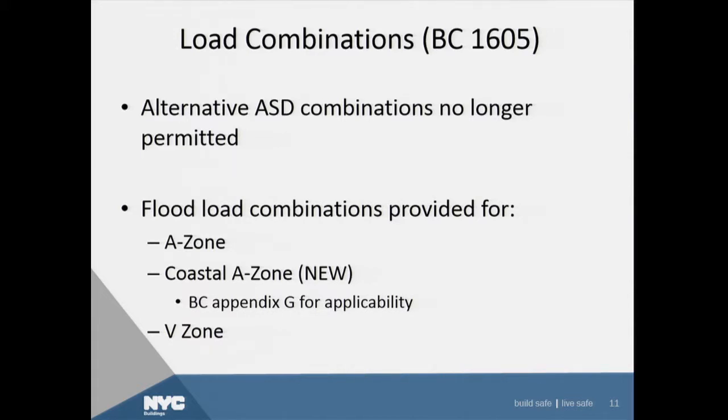And as part of our further enhancements, there were specific flood load combinations provided for in Chapter 16 to provide some clarity. The load combinations themselves you could have found previously by going through the reference standard and the building code, whether it's the IBC or the New York City code. You could have combined them all together to come up with the appropriate load combinations, but the committee got together and put them in directly for you.